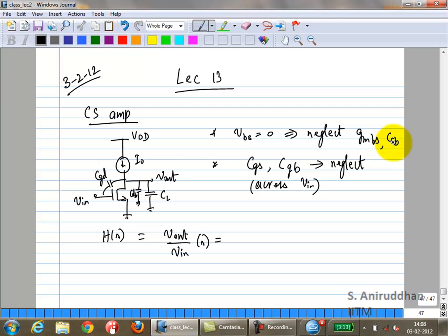First of all, what is VGS at very high frequencies? If I plot VGS as a function of frequency, I am applying an input source, right? Okay. Obviously, now you need to start assuming, if you are going to start considering CGS, you need to assume there is some source impedance. So let's do that also. I'm going to move this a little bit down.